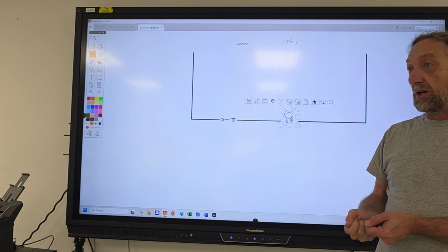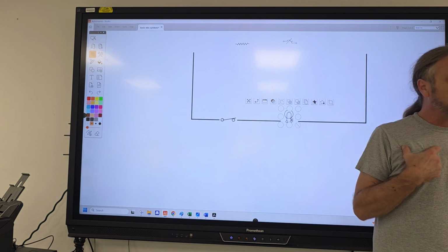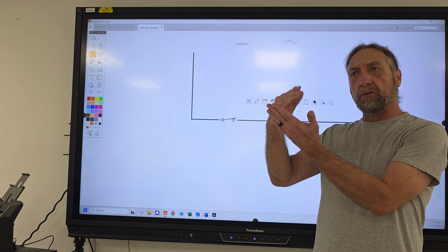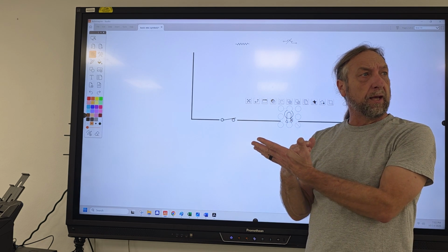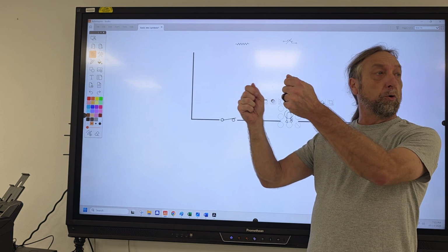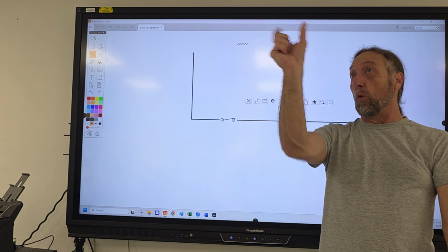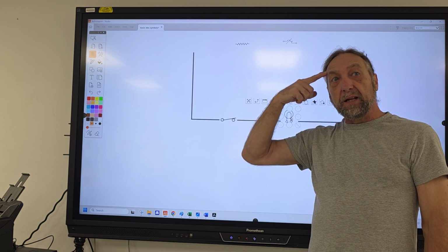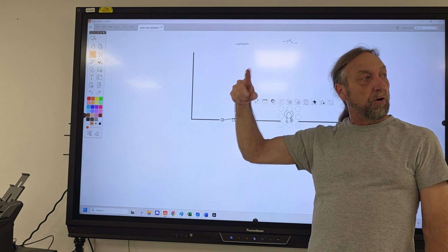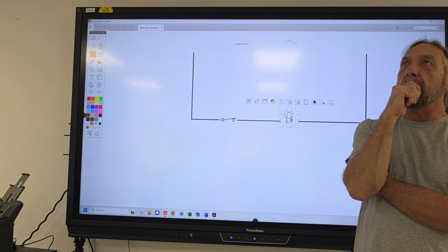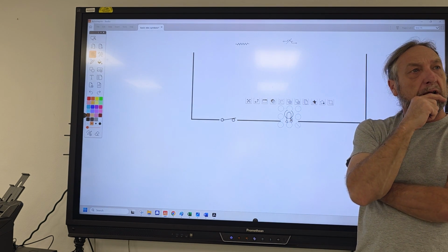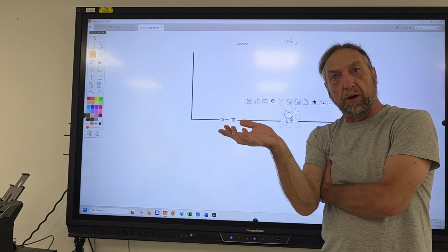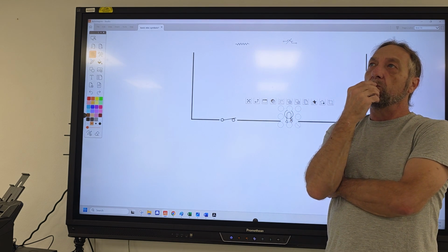As a technician, you go into your office, or let's say it's your own company, and you have a certain amount of customers to do that day. You're going to look at Ms. Jones, the first customer, and it's going to say washer does not drain. Well, immediately in my head, wheels start turning saying, okay, it doesn't drain. The drain pump may not be working, so the problem may be with my drain pump. Yeah, she already did the job for you.